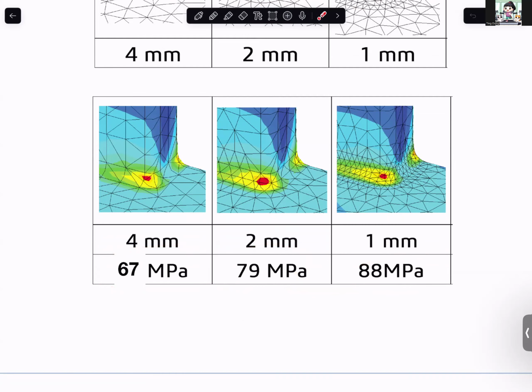And you probably could figure out if I take half of the size, and if there's a great change in the stress result, it means that it's still far away from converge. It's still far away from the accurate results. But if you keep refining, let's say we can keep doing this, not just reset the data, you can keep doing it, until the time you take half the size, but the stress does not really change much. You know that you can stop there. There's no point in keep refining and taking longer time to run the software.